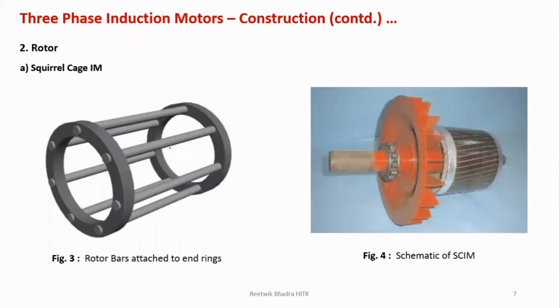Now going into the rotor construction. This is the stator part. The stator for any induction motor, maybe a squirrel cage motor, maybe a wound rotor motor, has fixed connections. The only difference we had seen is the rotor construction. So see the rotor construction over here. These are copper bars, conductors. This looks like a cage, right? So this is a cage motor.